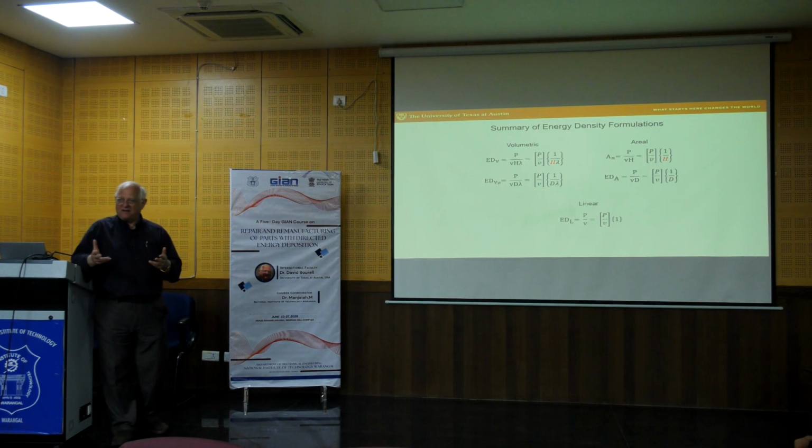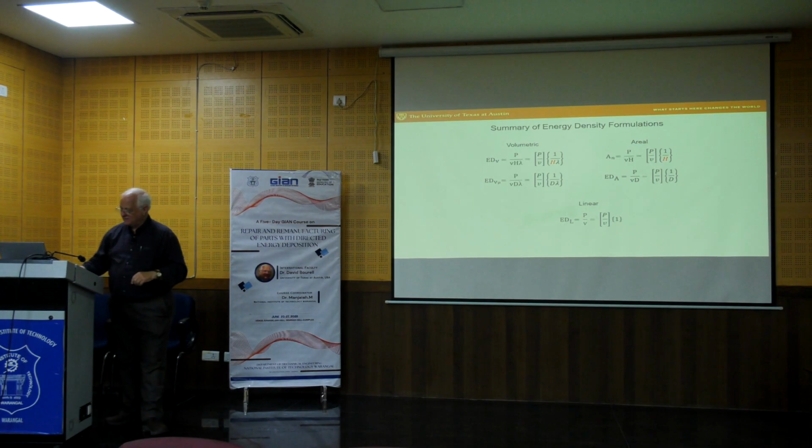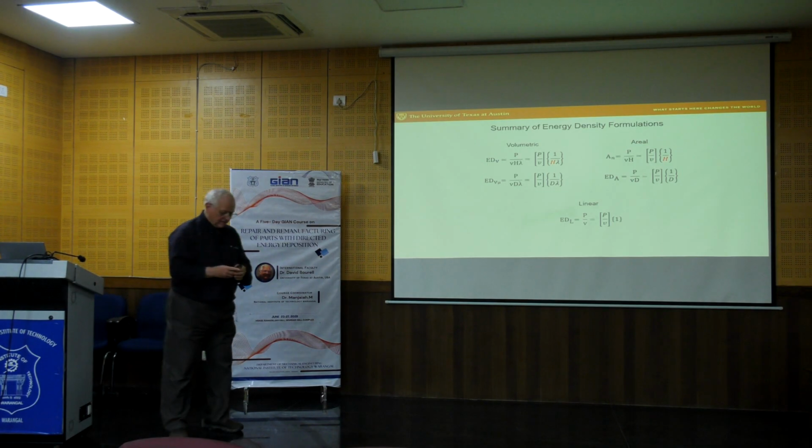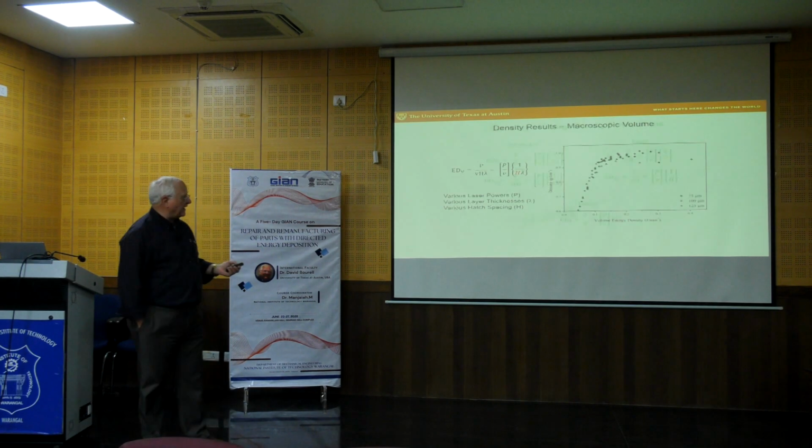It was done with nylon, not with a metal. But to ascertain which of these is really the best, and in this case, I varied the beam size and the diameter and the layer thickness so that we could see and probe more completely which of these was doing the best job of predicting good density and good mechanicals.